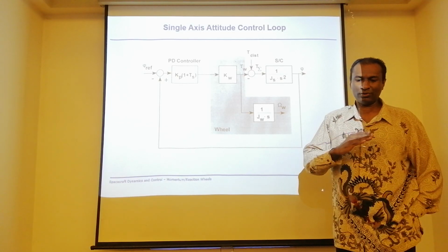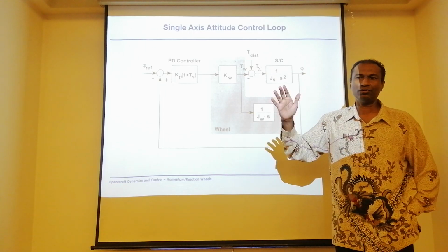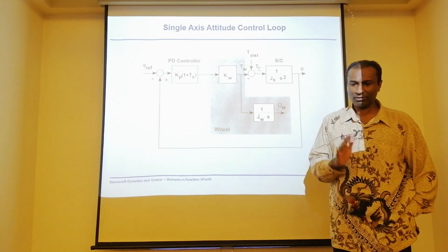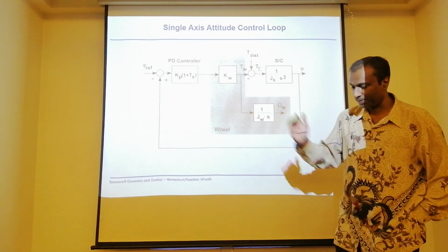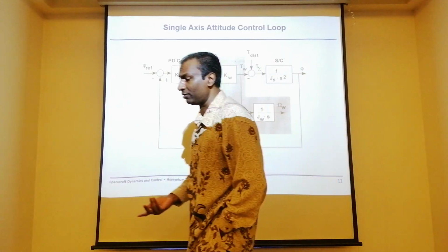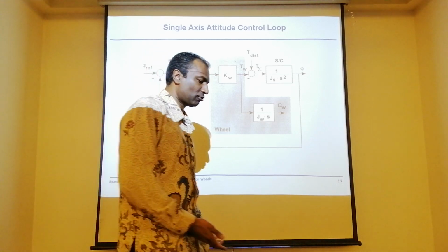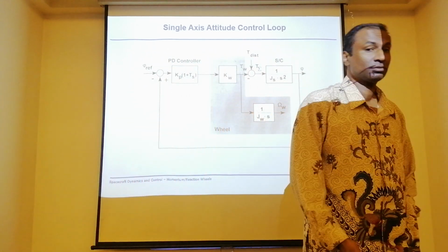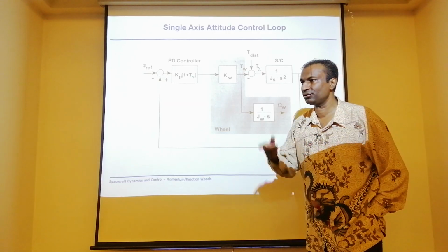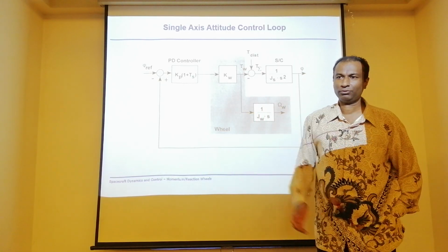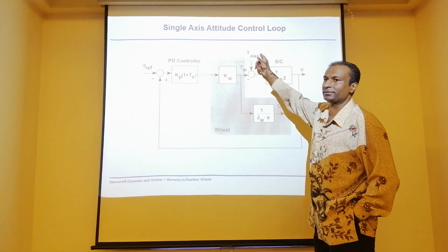Okay? You accelerate the wheel, you will have a positive torque. You brake the wheel, decelerate the wheel, you will have a negative torque. Please understand that. So in order to brake the wheel, you must have a torque. So what we can do, we can add another device, and a typical device that we know, which is very, very common, we can use magnetotorquers. And magnetotorquers is going to give torque. Let's say B dot. You do a B dot pointing, just give a torque. Keep on adding the torque here.